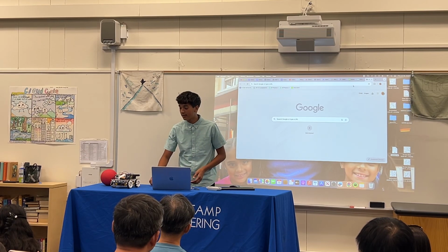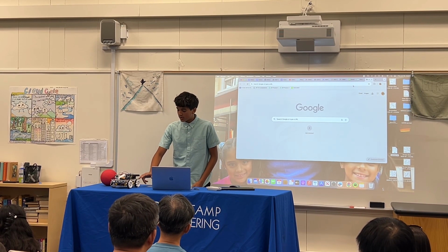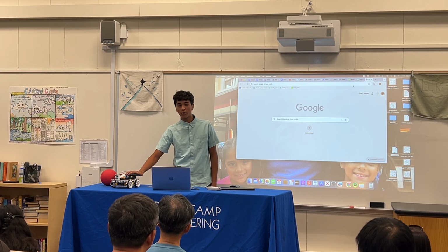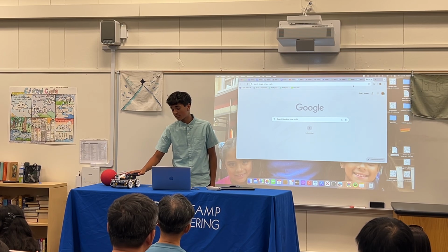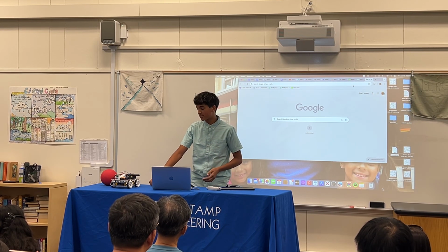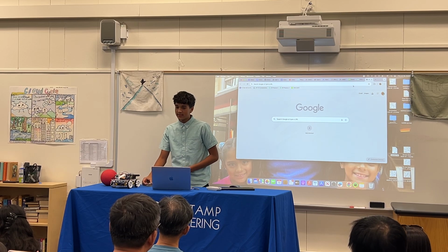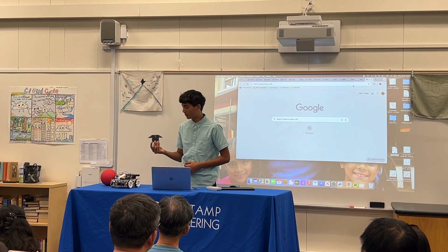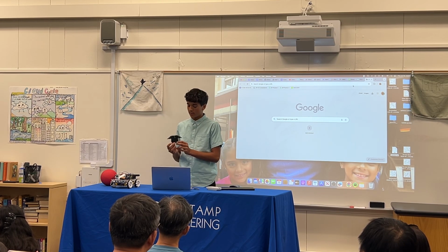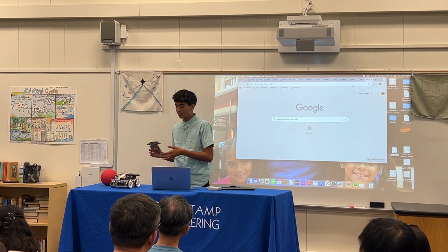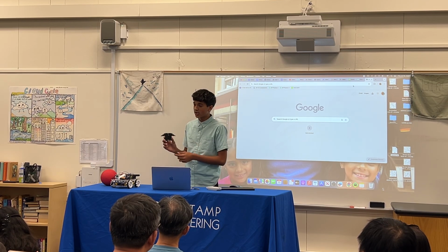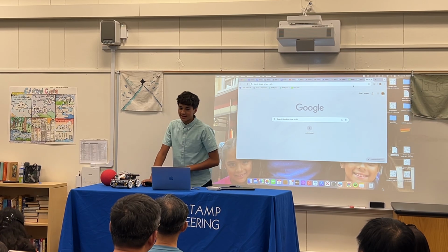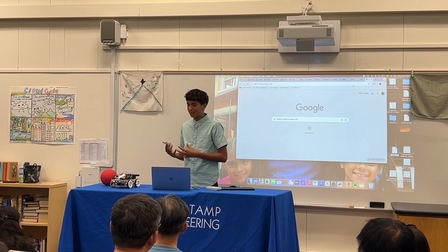The final problem I had was with the circuit. So with these new Omni wheels, I had to add a lot more wires, and I was pulling too much current, or there were too many things connected to my Raspberry Pi, which was causing it to crash or shut down. One way I solved this problem was I designed a PCB, or a printed circuit board. This is an electronic assembly which replaces wires and a breadboard, which I had used originally, that creates connections with copper. I use this PCB for these electronic sensors as suggested by my mentor, Landon.